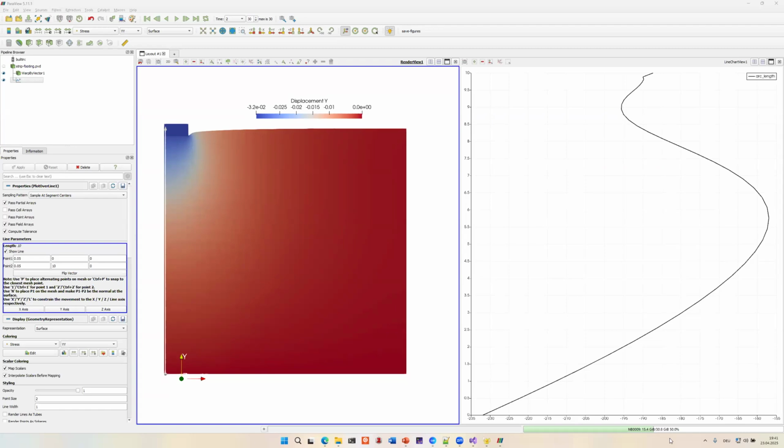Is that what you're aiming for? I'm thinking more like some software like Plaxis, which has some issues when we try to lower the mesh size to very small mesh lengths. We get mesh dependency in the results. So you understand what I mean?